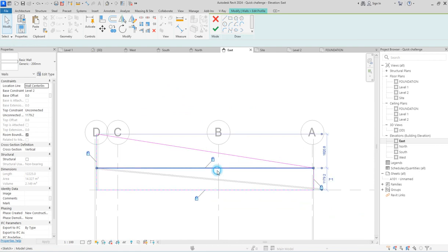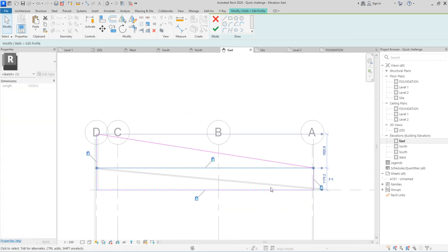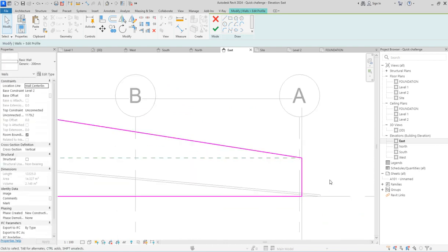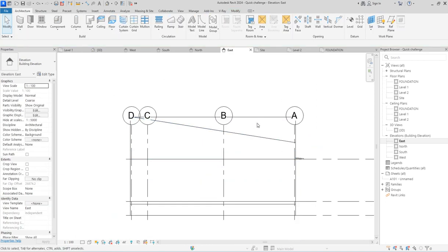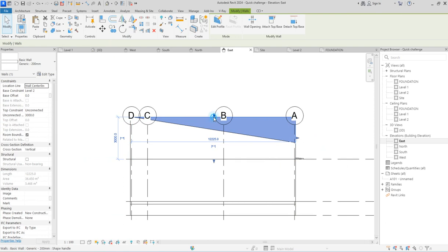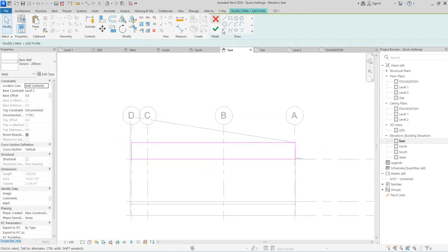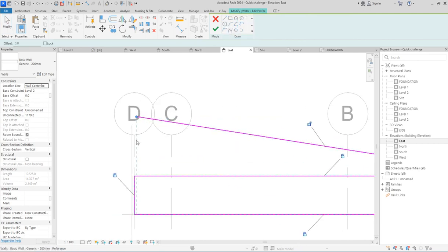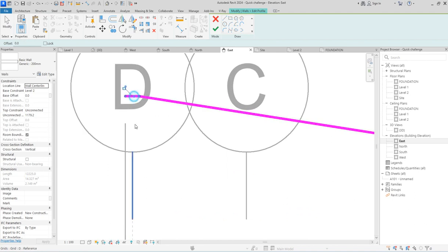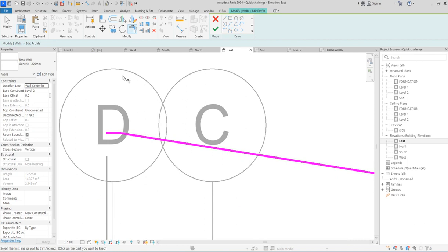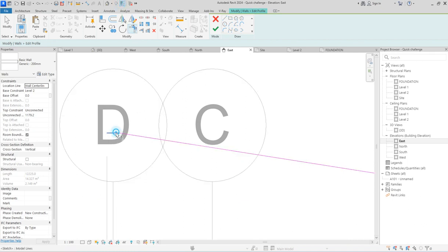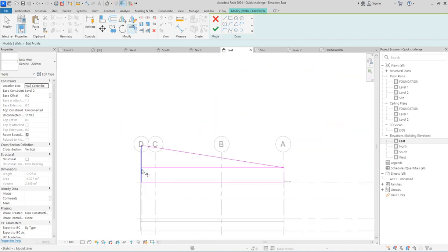So what you do, select this middle one and delete it. So no use for the drawing anymore. So click finish and see if there's any issue. So no issue is mentioned. So you drag this one again to that same position. So you edit the profile by using these guys. So instead of you doing your own thing, just select this and let it match up with what you've done. So it will match and you trim the way you have done with this one. So all this so that I can be able to see the line clearly.